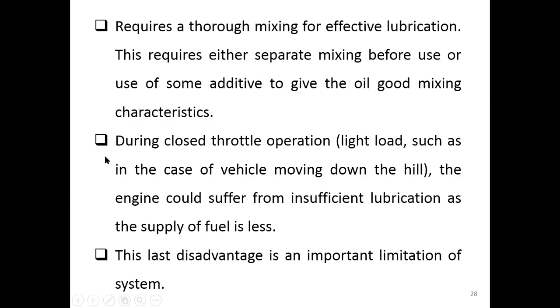And since the oil has to mix with the fuel in order to perform the lubrication, this sometimes may create a problem. For example, under some engine operation, such as light load, for example when the vehicle is moving down the hill, there might be insufficient lubrication, because when the engine goes under light load, the amount of fuel is less.